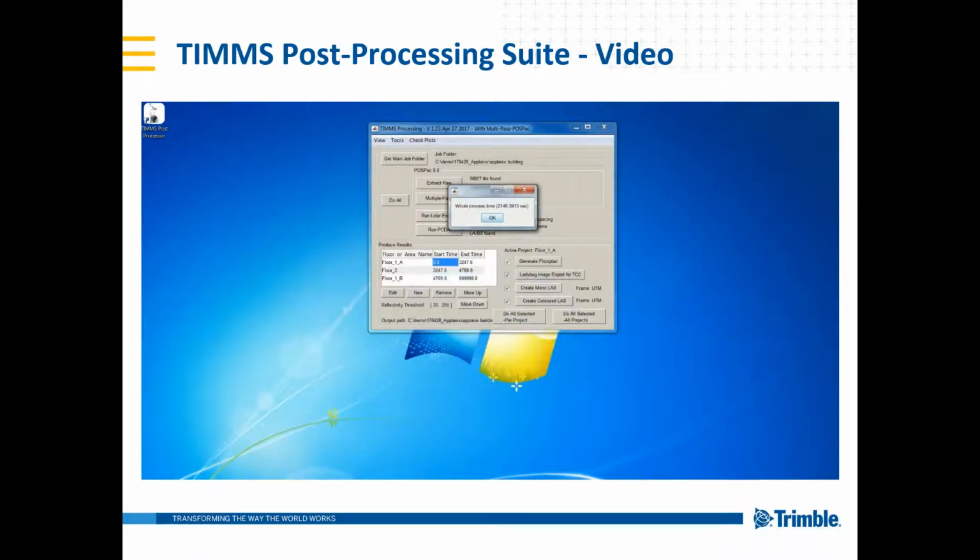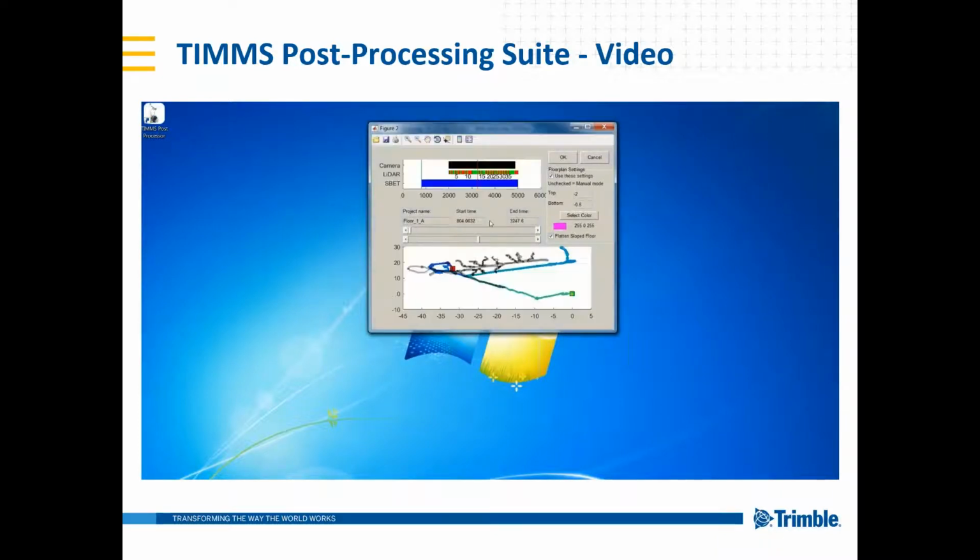So we quickly went through the INS processing, and we've fast-forwarded again through the point cloud adjustment. That step, for this data set was about 1.5 hours of data collection. The navigation processing and point cloud adjustment was about 40 minutes. If you were quick, you saw a little counter there that said it took about 2,000 seconds or so.